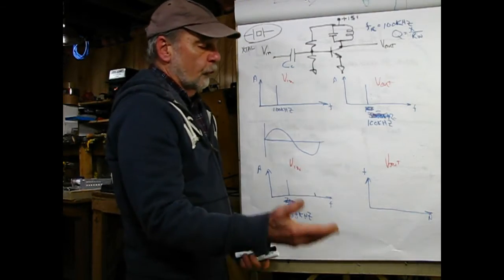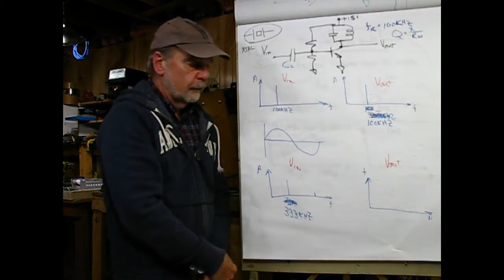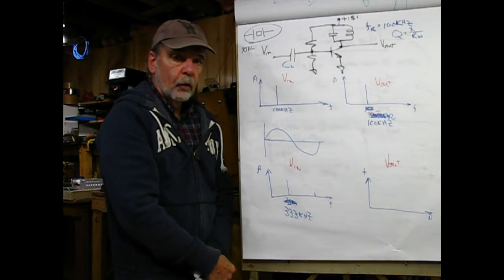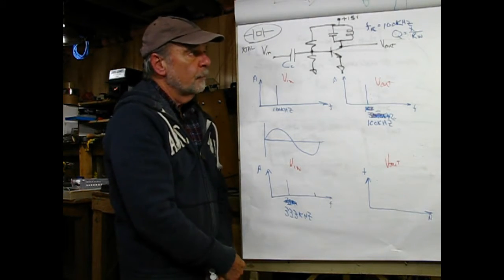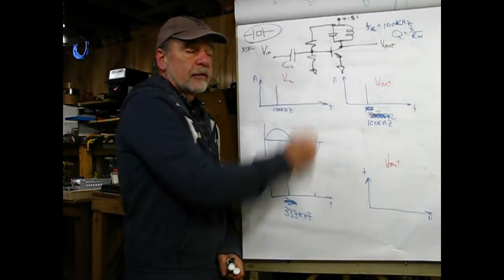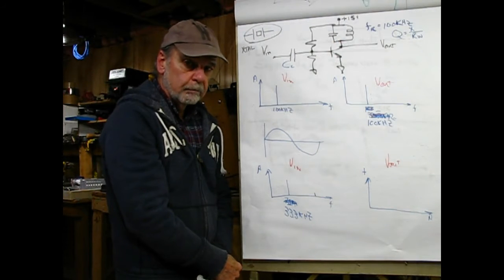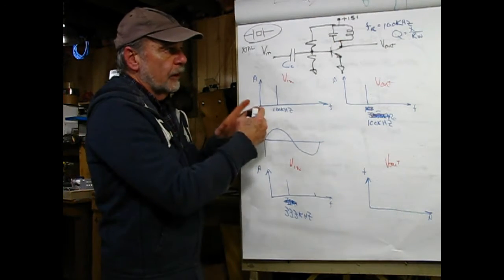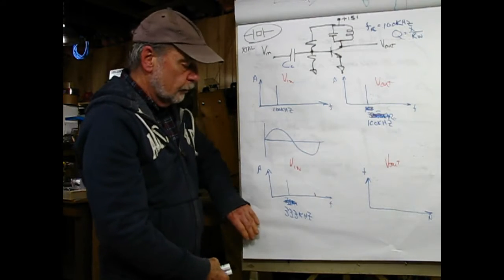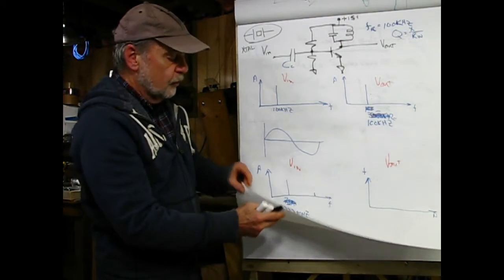Now here we're also assuming that we have a reasonable Q, its quality factor, which is defined by the reactance over, in this case, the winding resistance. And the reactance at a Q greater than 10 of an inductor and a capacitor has the same magnitude. So we're not dealing with a peak circuit, it's actually a tuned circuit. So not too much thrilling there with a sine wave, but let's move on a little bit.